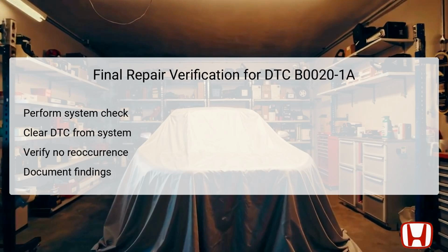After completing the troubleshooting process and any necessary repairs, the final step is to verify that the issue has been resolved. This involves performing a complete system check to ensure that all previous DTCs have been cleared and that the driver's side airbag system is functioning optimally. Utilize a diagnostic tool to clear DTC B0020-1A from the system